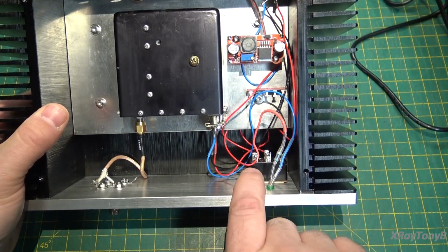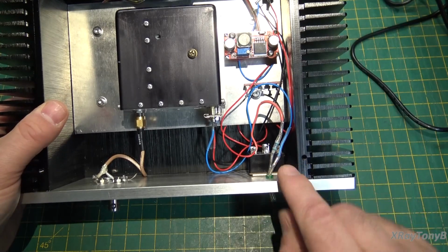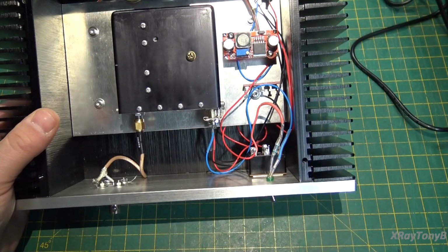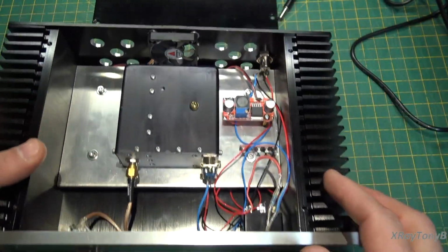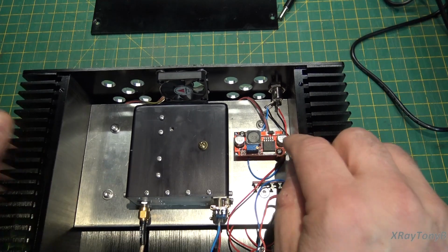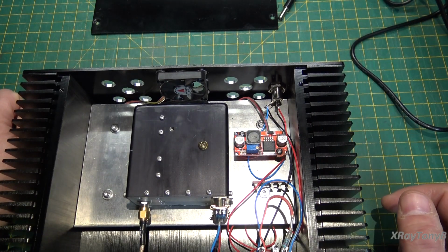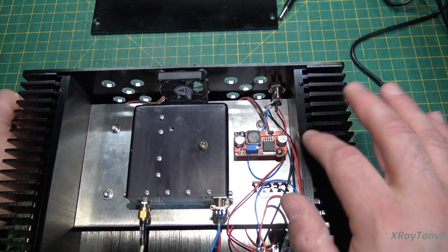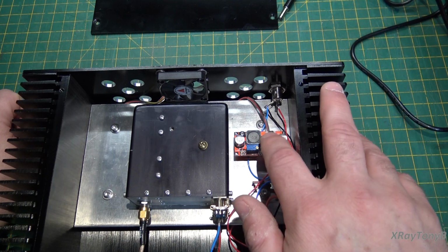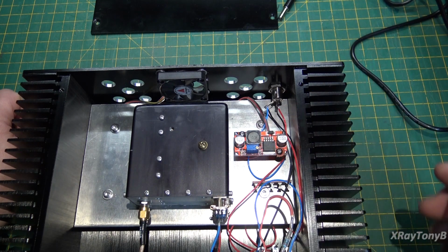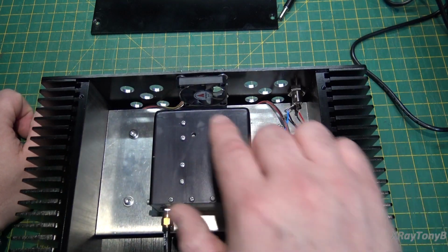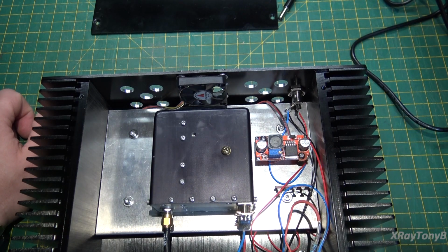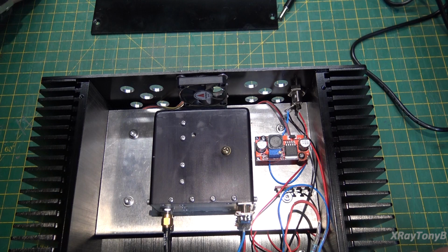I put an on-off switch, and this is the lock LED with the appropriate dropping resistor, and they're all wired into this connector here, the DB9 connector. And if you notice, I have this little buck converter. It's a little DC to DC converter, and basically this thing runs on 15 volts DC. What this is doing here is it takes the 15 and steps it down to the voltage that my little fan will run on, which is a 12 volt fan, and I have it dialed down to about 11 volts, so it's a little bit quieter and a little bit easier on the fan.